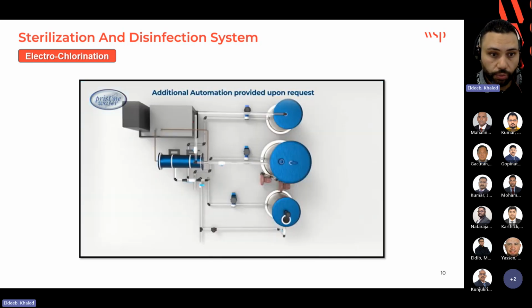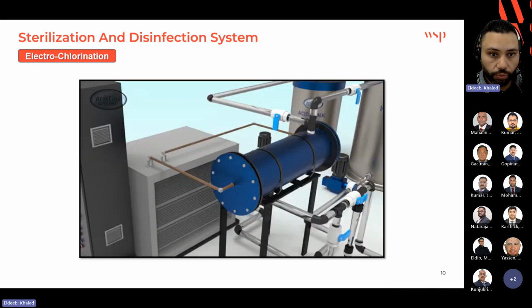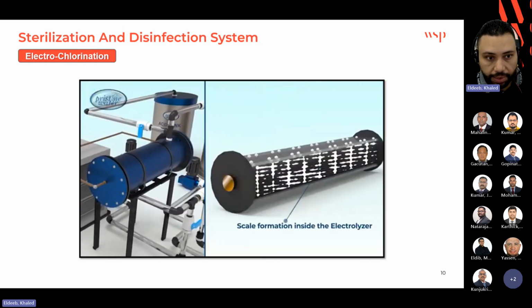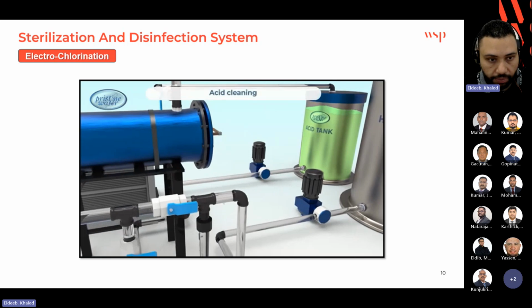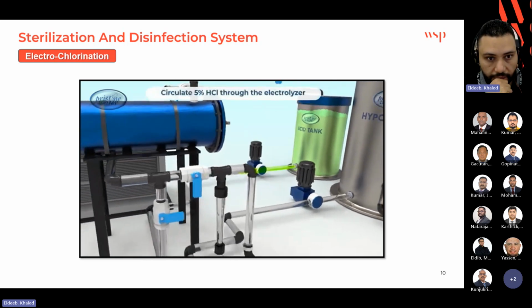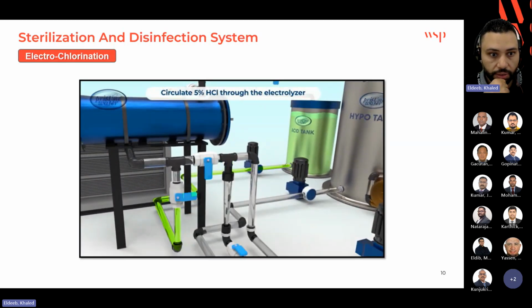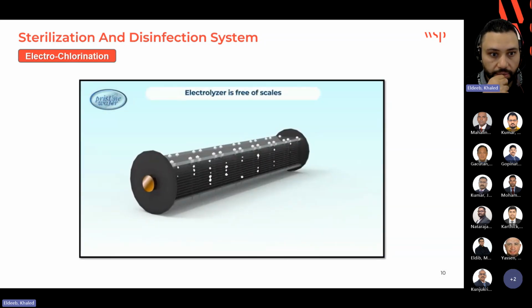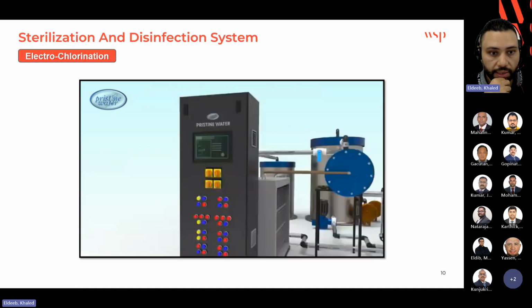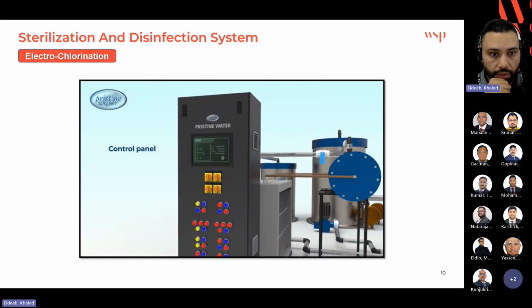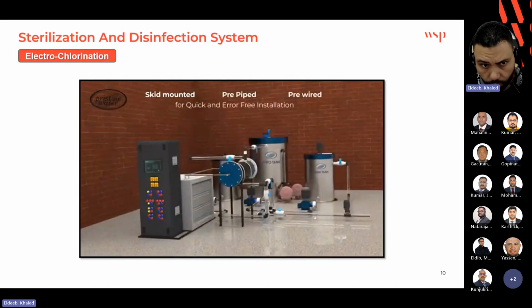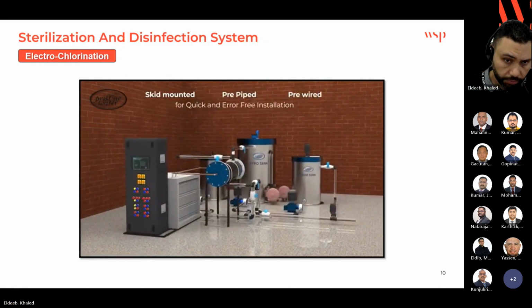It is provided just to provide auto cleaning for the electrical rods. You see here the scale forming around the rods. It impacts the efficiency. So every month or every 2 weeks, automatically the system takes the chemicals from the tank to clean it, and returns them back again to ensure the system is efficient all the time. Okay, so it could be 2 or 3 tanks or whatever.